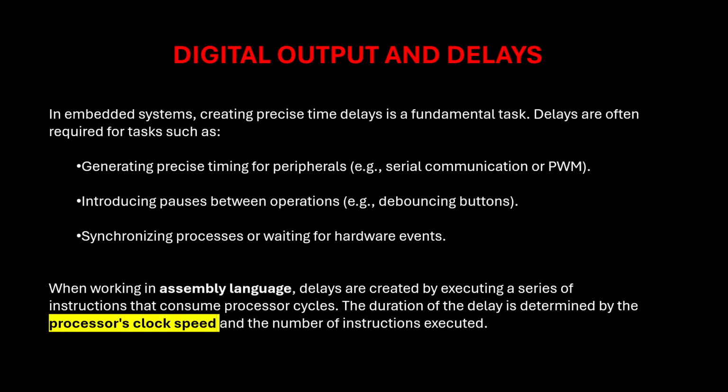So, in embedded systems, creating precise time delays is a fundamental task. Delays are often required for tasks such as generating precise timing for peripherals, for example, for serial communication or for PWM signals. Actually, in PWM, the time is critical, okay? Then it is also widely used for introducing pauses between operations like debouncing buttons.